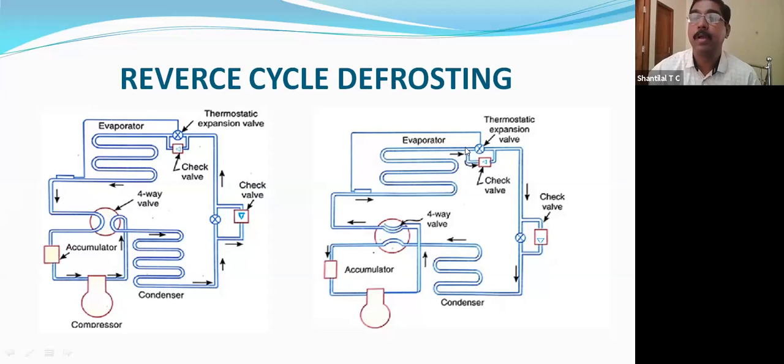Now the refrigerant is going through the check valve, through here the refrigerant is passing. This other check valve is closed, and this is a hand expansion valve. Here it is opened. After expansion, the pressure is reducing. Now this condenser will act as evaporator and goes back to the compressor. Like this the cycle is reversing. So a reverse cycle means the evaporator is changing to condenser and the condenser will change to evaporator.